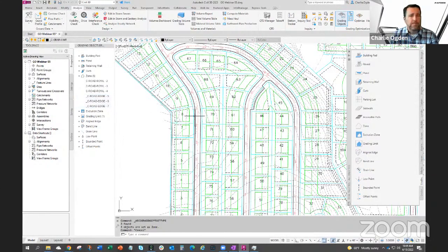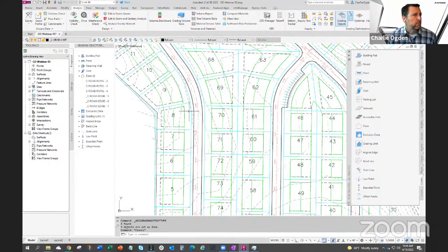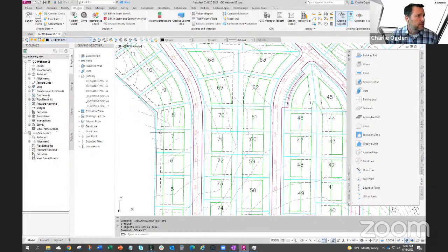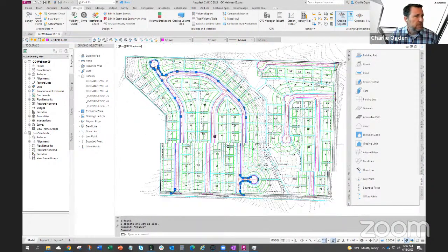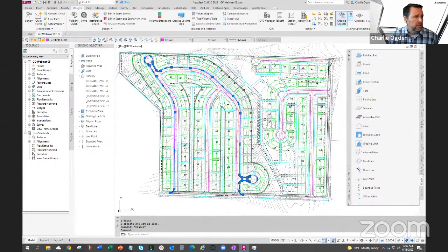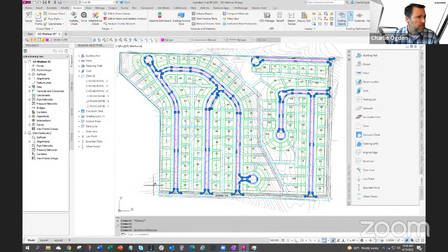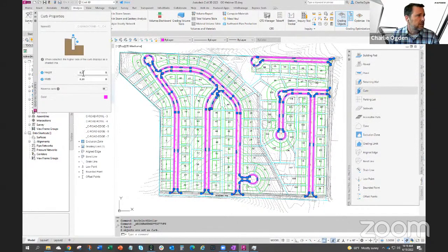And then just to better define the roadways, I'm going to turn on some geometry for curbs. So you can see I've already connected all these polylines to have curb lines. And I'll just select similar so I get all the curbs. Add these as curbs here.